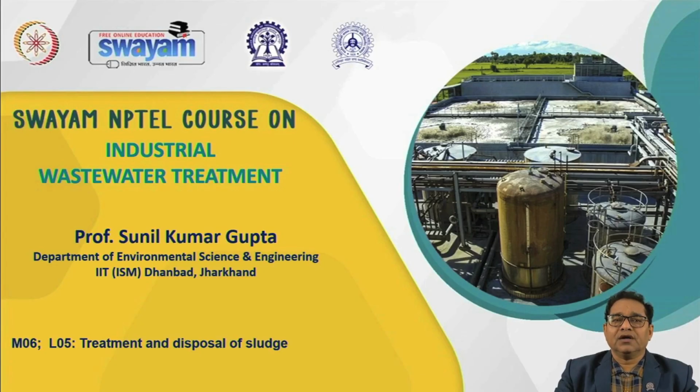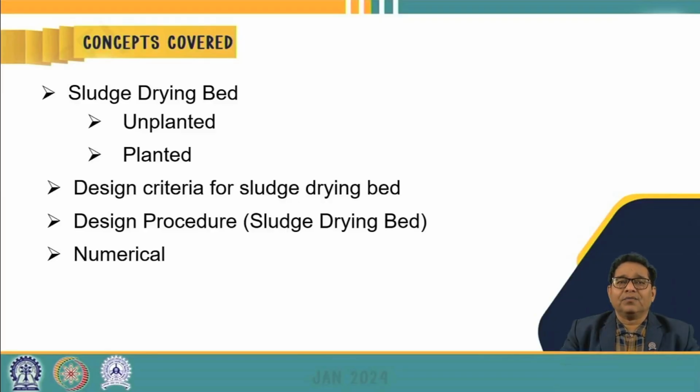Welcome you all. Today I am going to deliver lecture 5 of module 6, which is on the treatment and disposal of sludge. If we recall our previous lectures, we started with the sludge characteristics, various equations to be used to determine the quantity and volume of the sludge, and then we saw the design of gravity thickener, then the sludge digestion process, and now we are going to learn about the sludge drying bed, its design, and